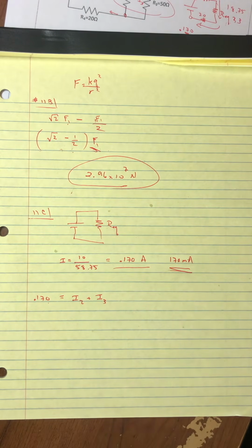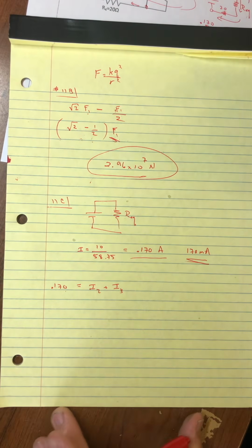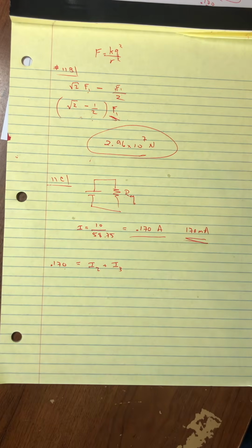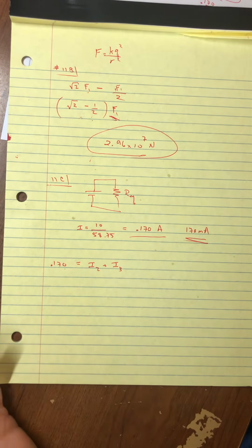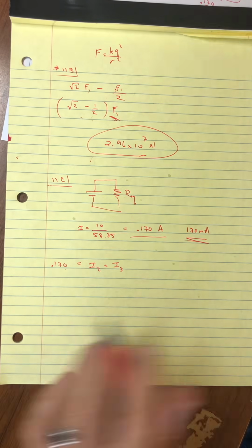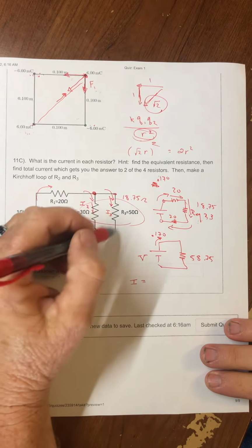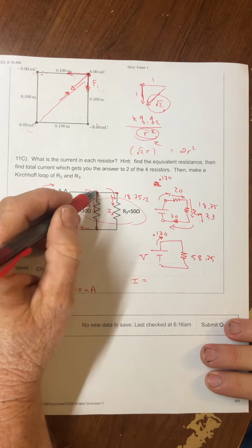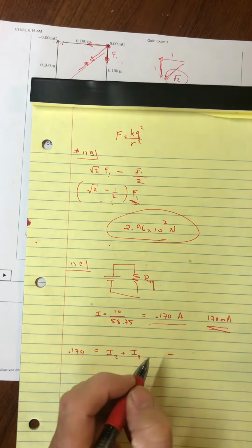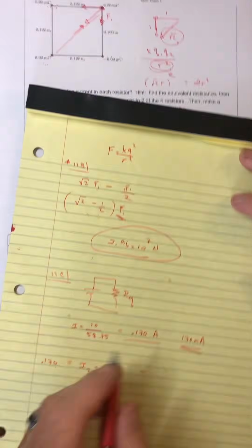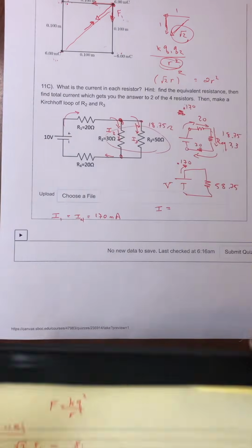And that's why we don't need to have a 3 equations, 3 unknowns type of problem like you might be doing in the lab. It's not that hard. It's only the 2 unknowns. So, of course, that means we need 2 equations. And so the hint of this said do a loop right here. All right, so if we start here and go with the current, now it would be a minus, since we're going with the current, and it would be the resistance of 30 times the current, which is I2.